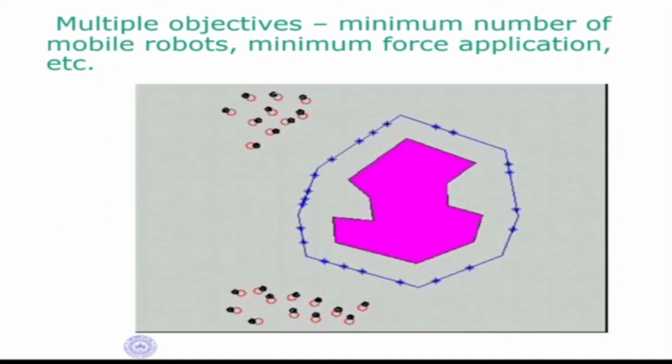So that is the objective of this path learning with multi-agents. Now this object is moving. So if this robot tries to go and sit here, the object is going to hit the robot. So it doesn't go and sit on the object straight away. It has an expanded boundary like this, on which the robot goes and sits. That is what we are seeing here.